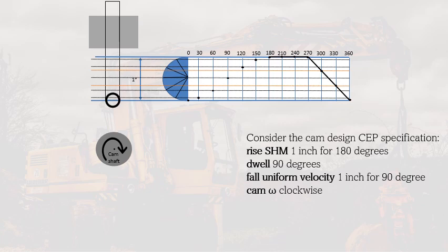After drawing that, we are also going to divide the cam into the same divisions that we have here in our displacement diagram, which is by 30. We'll divide it by 30 starting on the left side, because now our camshaft would rotate clockwise. It would mean that our first trace point would be on the left side. So we draw by 30 to complete the whole 360.